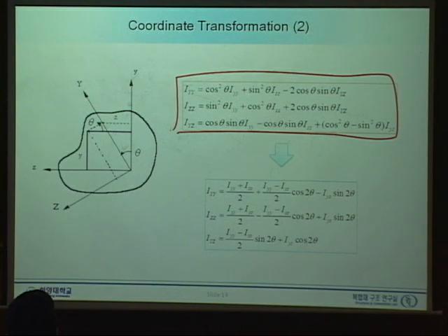And as you notice, this is exactly the same as stress transformation. So you can simply use a Mohr circle to calculate the moment of inertia with respect to an axis rotated by theta.